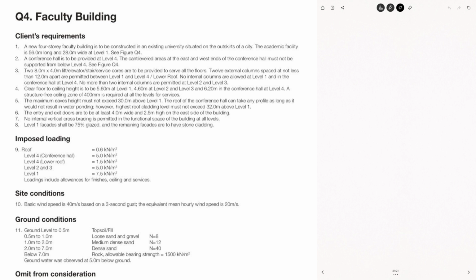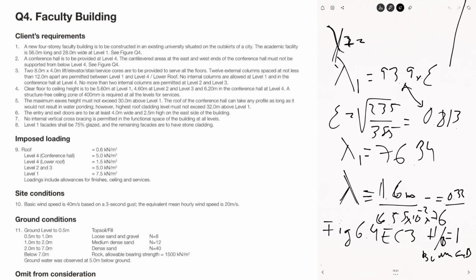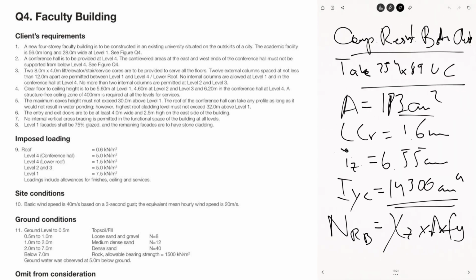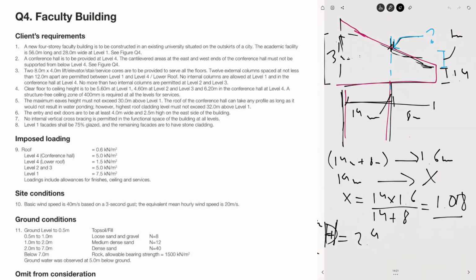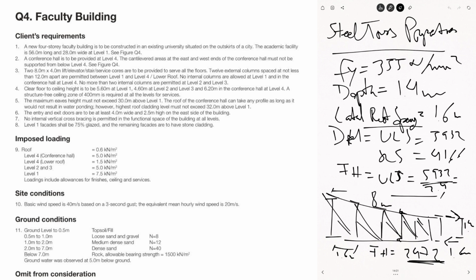And then using that value that we obtained for the inertia, we calculate the maximum deflection, which is going to be the SLS moment. This is an approximation of the deflection, and the SLS moment was 4166.